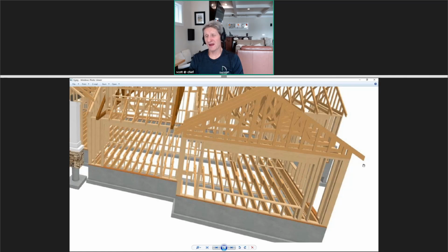You could open up the truss and modify it, but that would be quite a bit of work. I might just chop the truss off at the end here and then use a multiple copy with a little rafter that already has that profile on there. Then you could see it in 3D and in your section view. Might be one way to do it.